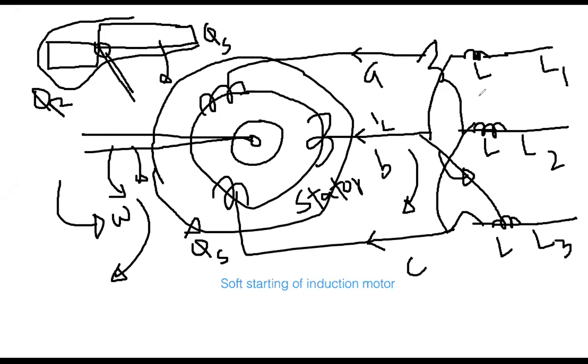Can you guess what is happening with the interchange? That is the phase sequence issue. It is somehow not matching with the proper phase sequence. So if you interchange, then your phase sequence is matched. Consequently, your magnetic field direction will be fixed, and finally your motor direction will be corrected. So you might face this thing, just interchange two lines. That is the meaning of the bullet there.